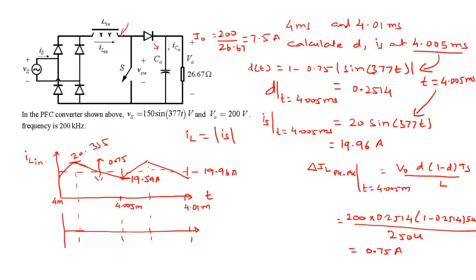All right. So this is the IC instantaneous waveform. It's going to be a constant at minus 7.5 during the switch on interval, then jumps to a value equal to this drawn IL in inductor current waveform minus the load current.